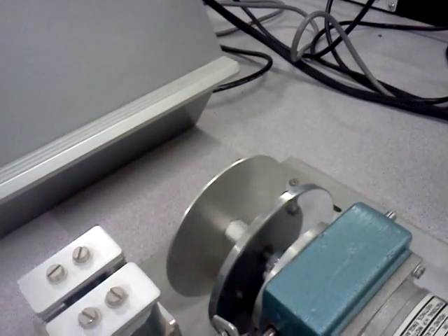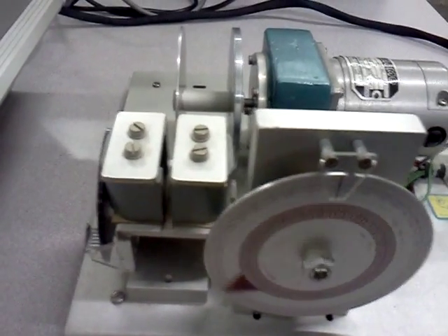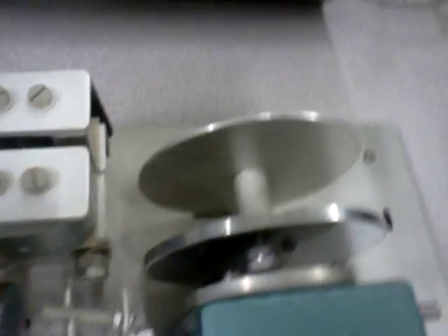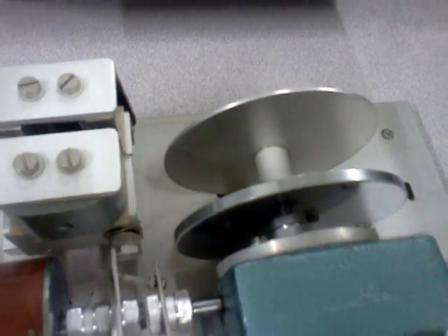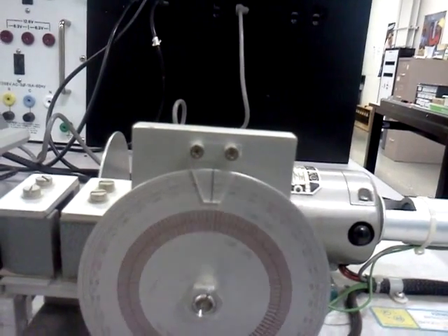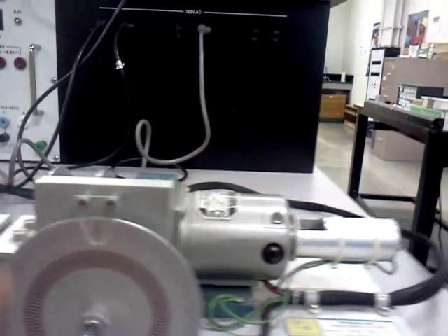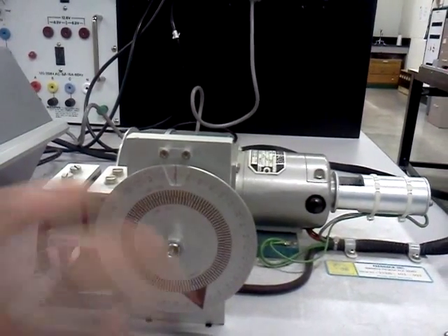Right now we have set for 0.3 Hertz input. And you can see that the motor is oscillating about 3 cycles per second. So you can see the motor spinning one way when the sine wave is positive, and then stops and goes the other way when the sine wave is negative. You can see the same thing here on the position output, which just oscillates. It should oscillate around 0. 0 is here, but there seems to be some 0 error here, but it's oscillating.